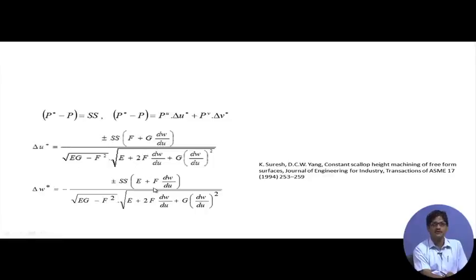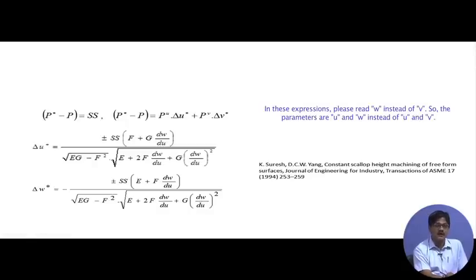Once we solve this, we get the magnitude, we have also got the direction, and we can pinpoint the side stepped positions. We pass a curve through this in the UW plane, and once we pass a curve through it, we truncate it or extend it in order to start and stop at the edges of the surface. Okay.